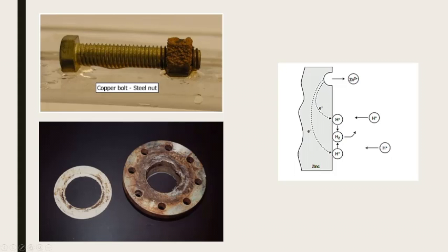There are several types of corrosions that can be seen, which includes crevice corrosion. It occurs in narrow regions like implant screw bone interfaces. When metallic ions dissolve, they can create a positively charged local environment in the crevice, which may provide opportunities for crevice corrosion. There is also pitting corrosion, which occurs in an implant with a small surface pit. In this, the metal ions dissolve and combine with chloride ions. Pitting corrosion leads to roughening of the surface by formation of pits.